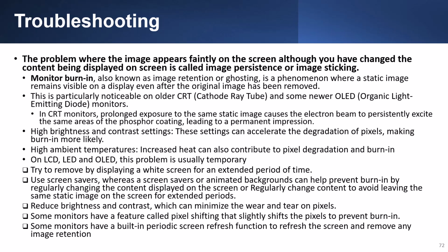Try to remove it by displaying a white screen for an extended period of time. Use screensavers or animated backgrounds, which can help prevent burn-in by regularly changing the content displayed on the screen, to avoid leaving the same static image on the screen for extended periods. Reduce brightness and contrast, which can minimize the wear and tear on pixels. Some monitors have a feature called pixel shifting that slightly shifts the pixels to prevent burn-in. Some monitors have a built-in periodic screen refresh function to refresh the screen and remove any image retention.